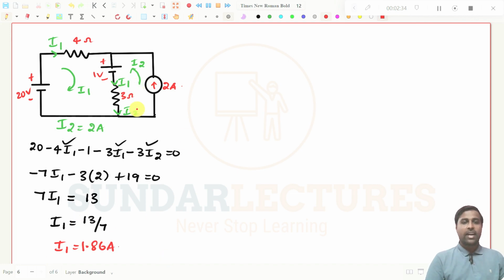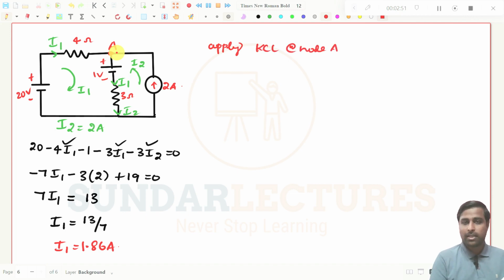That's all, right? That is I1, and we know what I2 is. It is very simple. You need to put a mark here at this point, and that is node A. So apply KCL at node A. This is I1, and this is I2, and we need to find the current in this direction, that is in the 3 ohms resistor.